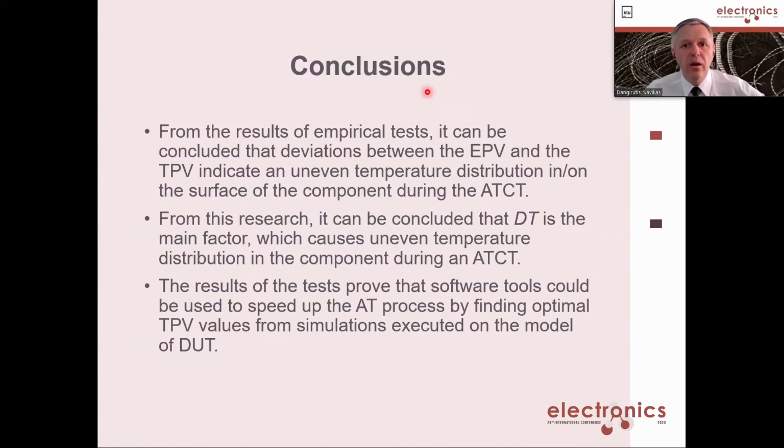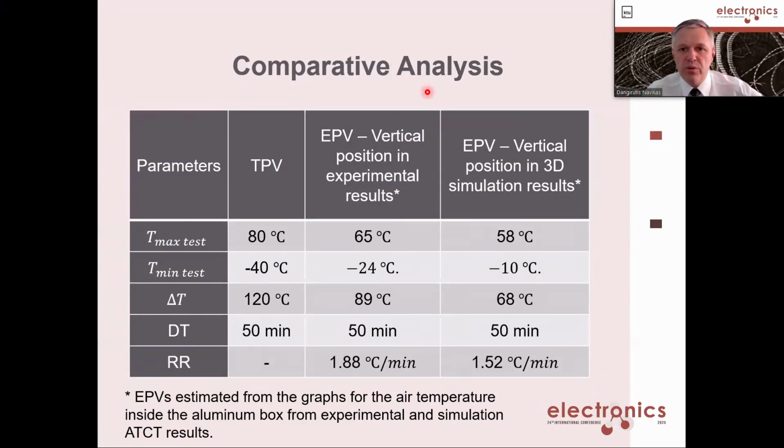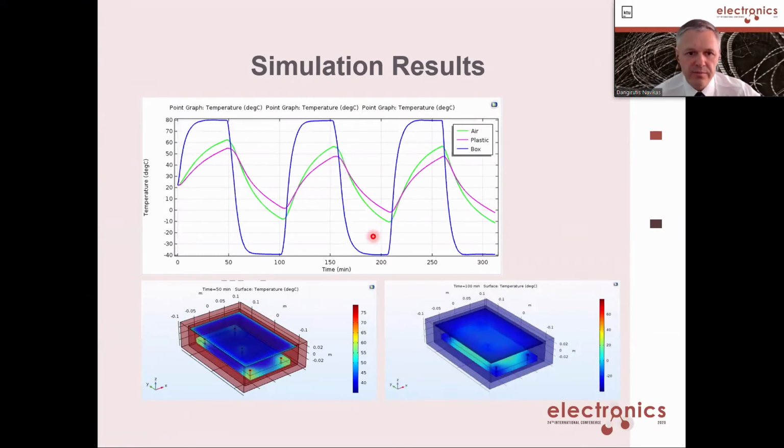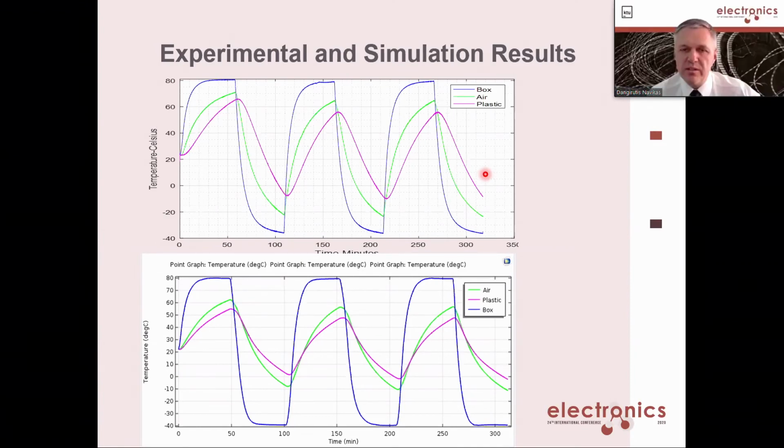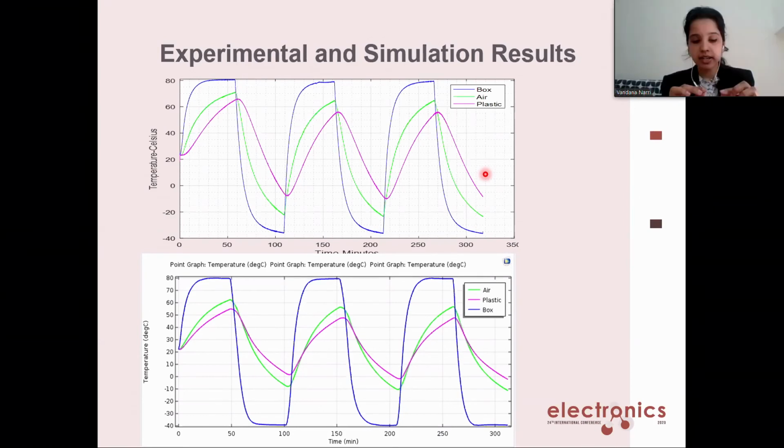So, how was the temperature measured in your real experiment on every surface? You mean in the real results? Yes. So we used temperature sensors located in different places. And we insulated them in such a way that we had the sensor, and then an insulator on top, so we made sure that it is not reading the temperature of the cabinet if it is placed on the surface.